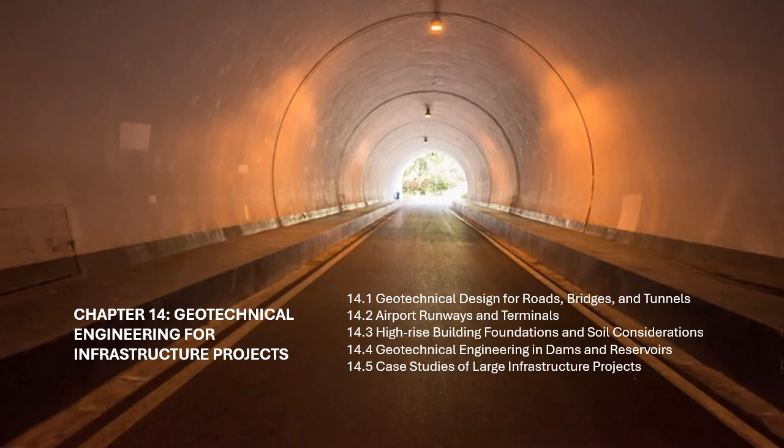Caissons, or drilled shafts, are similar to piles but are typically larger in diameter. They are drilled into the ground to reach deeper layers of soil and bedrock. Caissons are often used when deep foundations are required in soft soils or under significant loads.